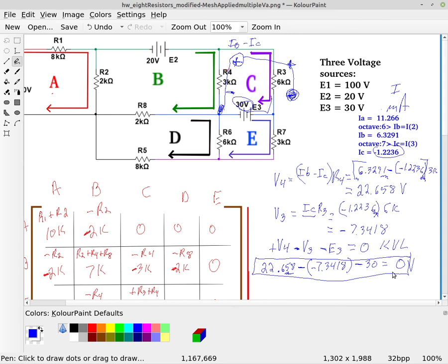And that will verify that all your calculations and all your entries, when you typed it into your calculator software, were correct. If even one of those loops doesn't add up to 0, then Kirchhoff's voltage law would not be satisfied, and so therefore you must have made a mistake. All right, but you only need to pick one loop, and you can double check that.